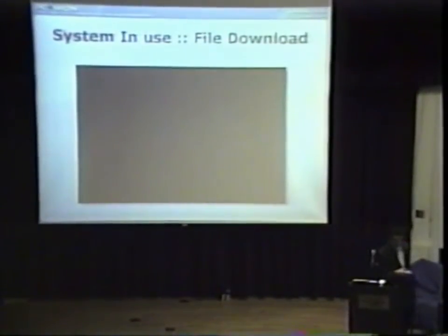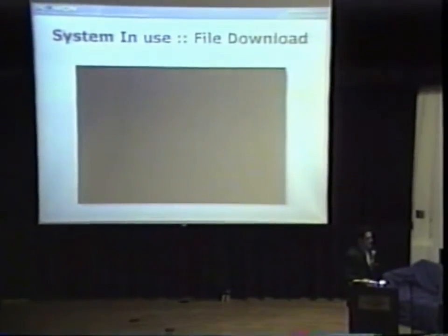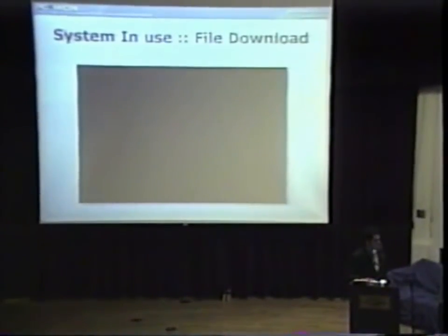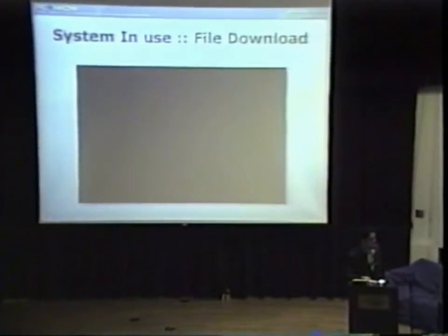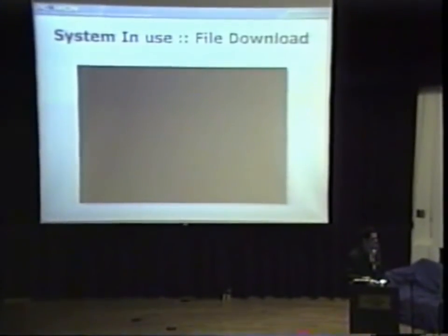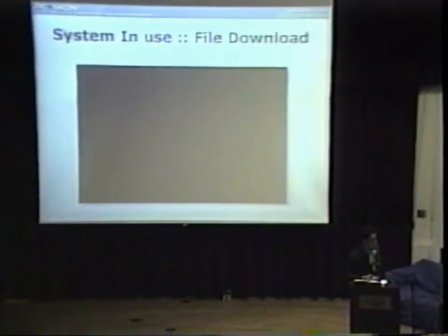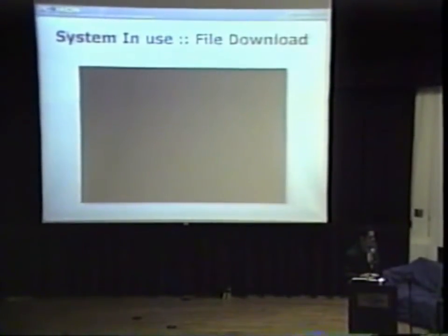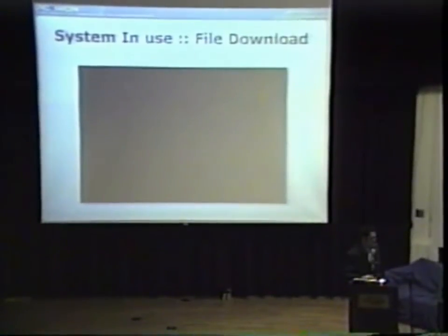So the user browses to their file, anywhere it could be located: on the floppy drive, the hard drive, the C drive, or even a USB thing. And you upload it, and then you enter the org address you want it to be located at in RAM, and you download it. The user then gets to see the instructions and the address those instructions are located at, which my software parsed out of the bin file.